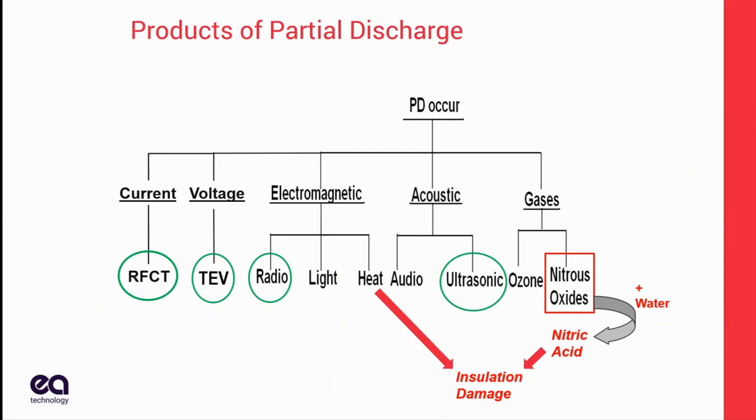The first effect I'm going to talk about is heat. Now, partial discharge is a very low energy event. It does not involve a lot of watts, so you don't have a big heat impact, but it is a very high temperature. So those are not diametrically opposed. It's plasma. It's very hot. By definition, plasma is in thousands of degrees, but there's not a lot of caloric energy in there. So what you get is local to it, you might damage the insulation. A couple of molecules of insulation maybe on each spark get damaged. It's slow moving, but that heat is going to damage the insulation.